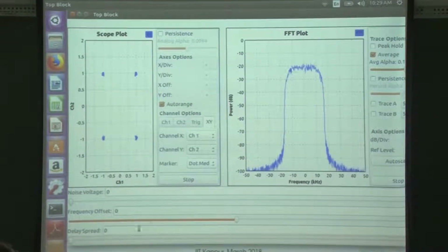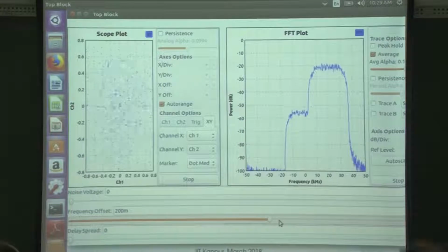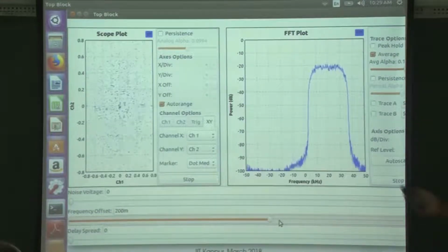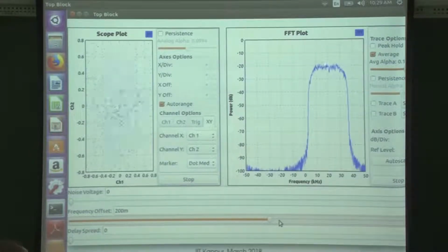But other things that communication engineers typically do not worry about are also a big problem. For example, there is something called frequency offset. If I just put in a small frequency offset, you will see in no time everything will be gone. So this problem we kind of put under the carpet, saying that look, we can somehow work it out, which is true, but under the abstraction that you can synchronize, you model noise and the channel, and then we have to get back the signal. So that's a challenge. That's how you can model the system. Okay. Now, any questions at this time?